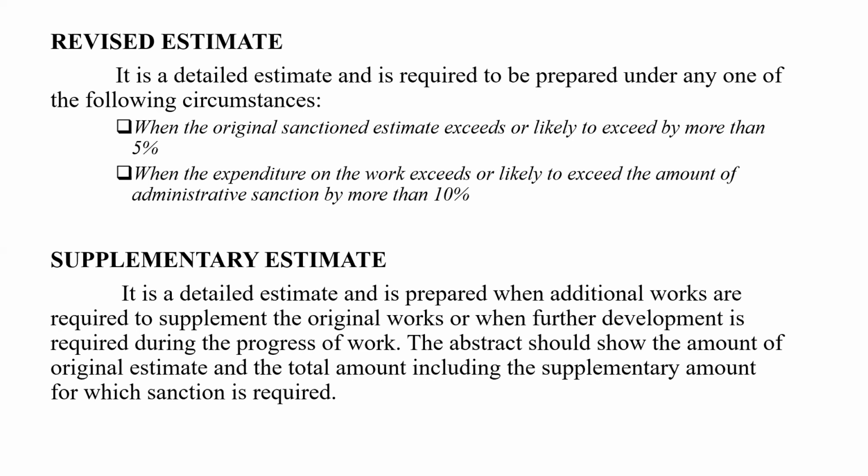The revised estimate should be accompanied by a comparative statement showing the variations of each item of work, its quantity, rate, and cost, and the original and revised side by side, the excess or saving and reasons for variation. And then now, supplementary estimate.